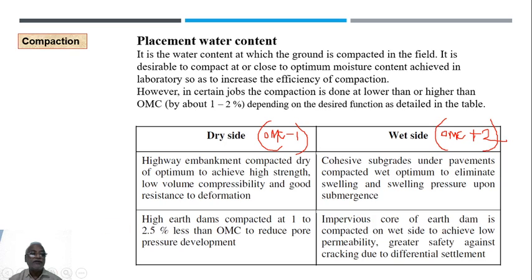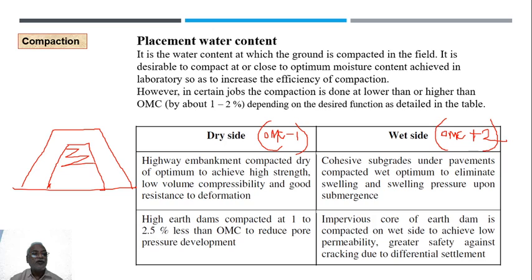So when you study an earthen dam, obviously an earthen dam will be having an embankment, something like that. So here there will be a small portion inside for which clayey soil or impervious soil will be used, so that when the water stands on one side, even if it penetrates into this soil, it should not penetrate into this, or the saturation line will be directly falling down. So this particular layer is known as the core, right?